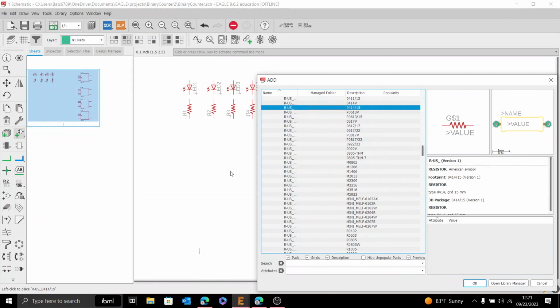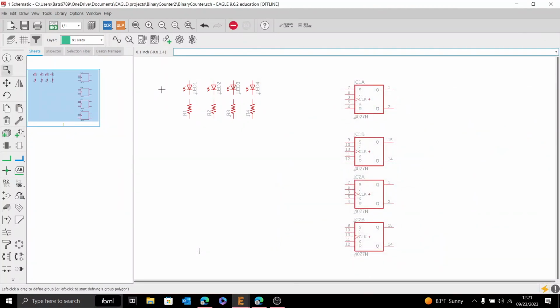You in the front. Okay. Could you expand a little? Good. Yes. Yes. Good. So, to say that for everyone else, we're going to take the voltage drop of the LED, which will be the forward voltage. Now, I happen to remember that the LEDs that we're going to order have a voltage drop of 2.1 volts.